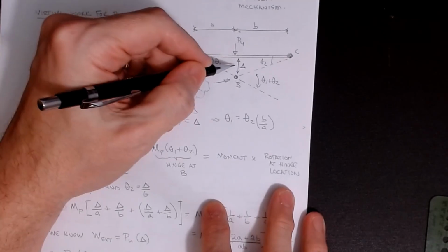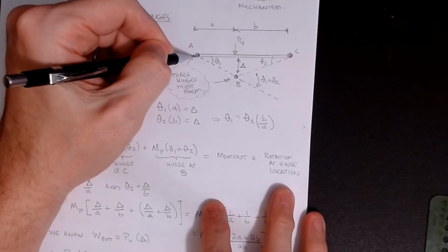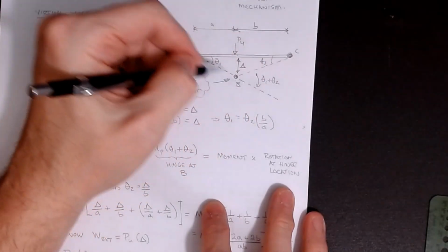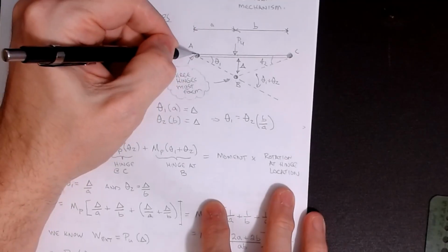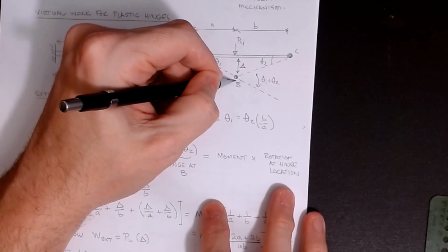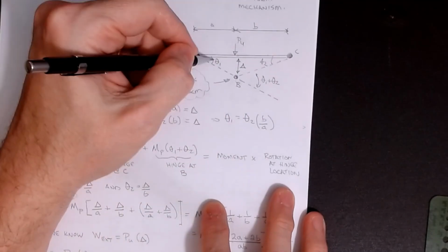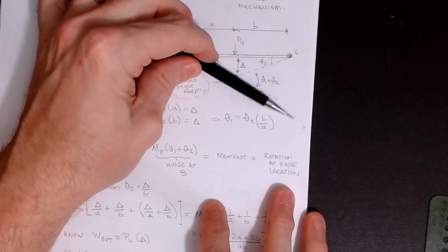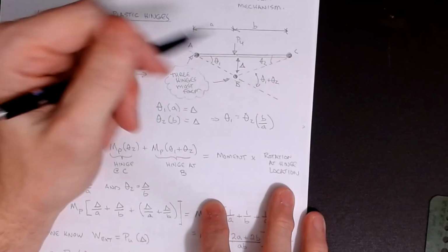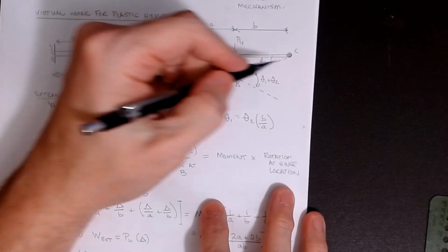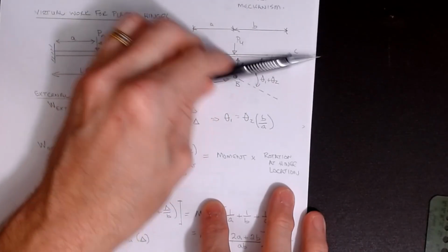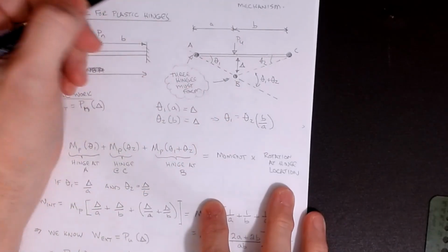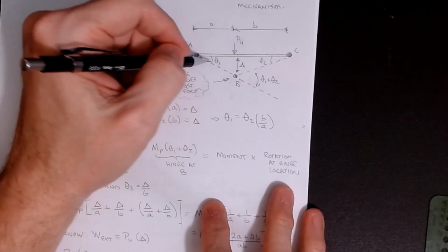All right. So when that delta forms, there is an angle that occurs at this left point that we're going to call theta 1. And all we're doing is straight lines that connect the dots. So the first line is the one that goes from hinge A down through the point at B and continues on. Originally the beam was horizontal and it wound up here, so it moved through a rotation of theta 1. And likewise, when this point comes down, because that was the support, then this line started out here, it will end up here. And we're going to call that angle that it moved theta 2. And then we're looking at the magnitudes of the angles.